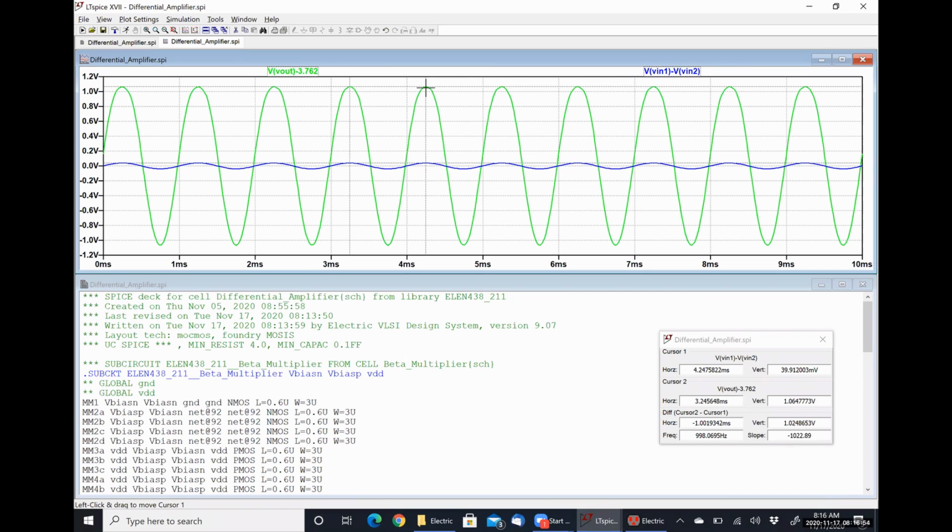So I couldn't begin to tell you why LTspice does poorly at representing small AC signals on top of a DC offset. But LTspice does a data compression, and the tolerance is, for mine at least, set to 0.0025, so it's too high for an AC signal that small relative to the DC offset, but you can change that.